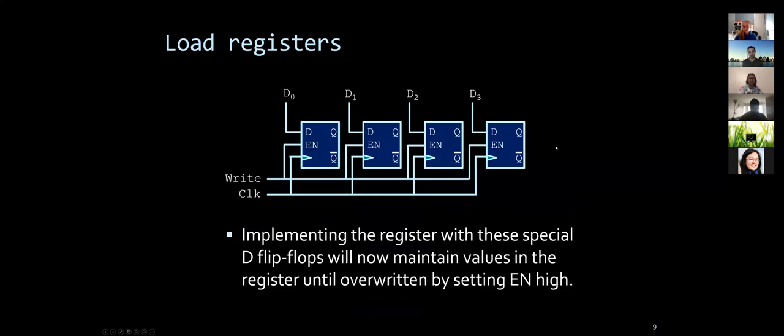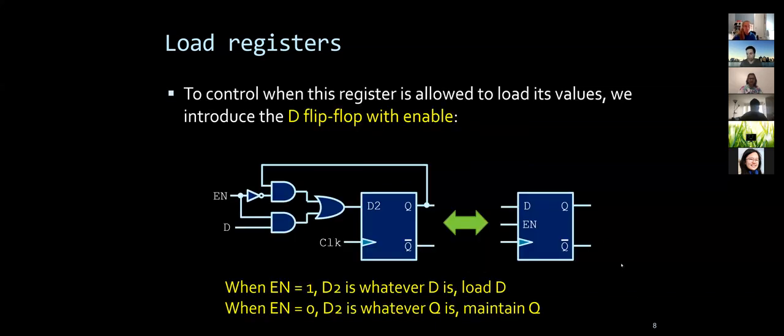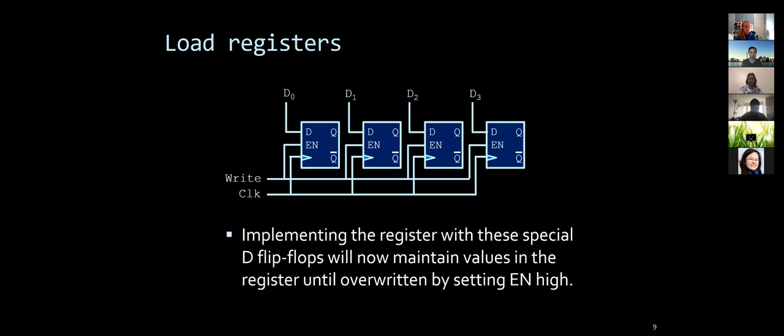Okay. So this is the D flip-flop with enable on, and just for everyone to remember, the difference here is that it has this EN in the middle, right? So I hope everyone gets it. It's not a fancy complication here. It either operates as before when enable is 1, or when it is 0 it just maintains the old value. We keep going to build the register.